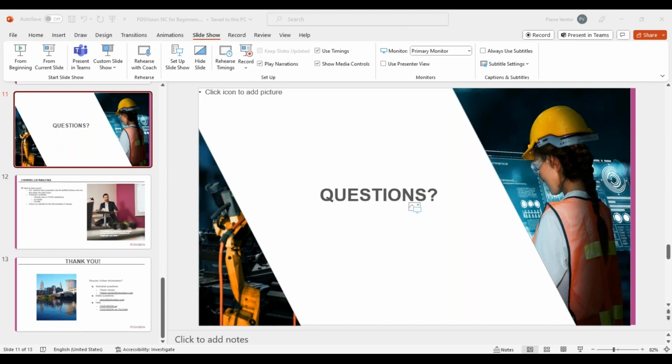Then the next question: are there default values for your RPM, feed rates, and so on settings? Yes, there are out-of-the-box values that you can use. Default values are just a setting you have to set when you specify your cutting tools. It will be a percentage of the tool diameter, so it's sort of driven from that. That being said, you can also change those relations, so that will get you closer to your working environment. There are default values, and how they are calculated, you can manipulate as well.